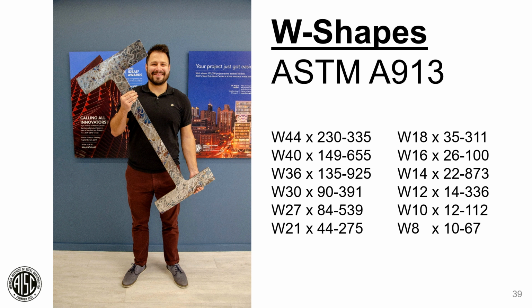One of the advantages of this grade is that preheat is not required for welding grade 50 and grade 65. What does preheat mean? As material gets cold, like around 30 or 32 degrees, it's necessary to preheat it to get to a proper temperature before you do your welding. Just think about trying to preheat that shape that Jonathan's holding there and how long it would take to get up to a proper temperature to develop the proper penetration of your weld. You may be preheating that for 24 hours in cold weather. So eliminating the need for preheat for grade 50 and 65 is an advantage. Grade 70 still does require preheat.